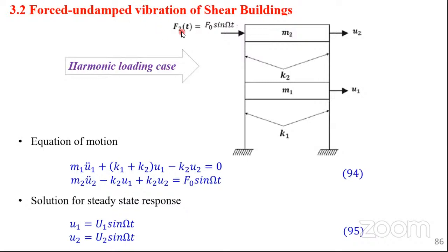And then we make matters interesting here. We said that at the first floor level, there is no forcing function. There is no externally applied load. So for the first floor, the equation will be free vibration. But for the second, we are applying the external load only at the second floor level. As usual, of course, mass is concentrated at floor levels. Columns just provide the stiffness. And the beams or the girder level is very rigid, so no rotation at the floor level.